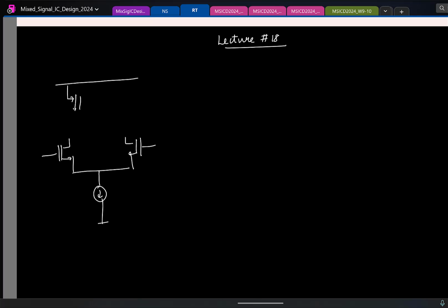So that's what you do. And of course, to make sure that the PMOS carries the correct current, you need to bias this voltage. And how did you generate this bias voltage without any redundancy? You do this connection and you tap this point and call it the output, right?